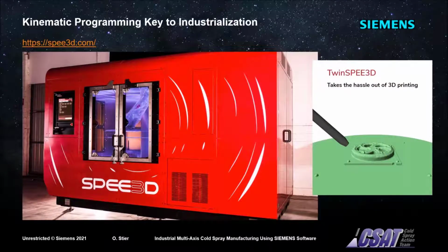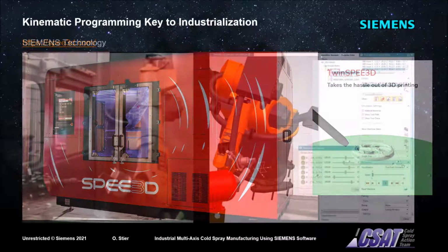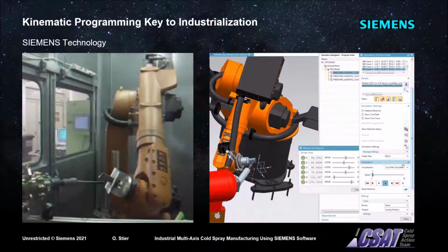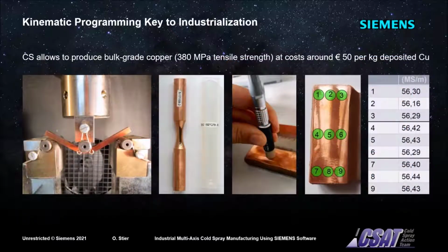The hassle, as SB3D put it, with automated cold spray production is mainly the robotic programming. In fact, the leap from producing test sample geometries towards programming cold spray runs for industrial coating, 3D printing or joining applications may be huge. In the laboratory, it is often sufficient to produce a chunk of good material and shape it by subtractive machining. The accuracy demands to robotic calibration are moderate in this case, and the kinematic programs are, more or less, easily written at the shop floor.